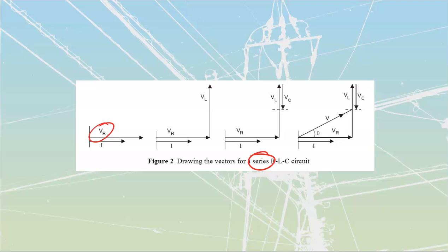What we get out of this is we are going to see a net vector, which is where we're going to end up, right? By the time we add this, and take this thing back down to here, we end up at this net vector right over there, and that's going to define our system. Now, the order that you add these up in would not make any sort of a difference. You could add in the resistor, then the inductor, then the cap. You could add in the cap, the inductor, and then the resistor. It really would make zero difference for where we would end up.